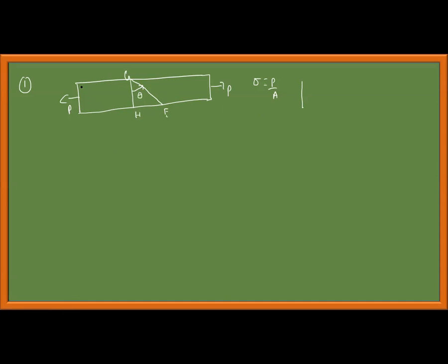Okay, the body is a long slender member, a bar. In the bar, if I take the stresses throughout along the length, the stresses are uniform. But if there is a plane at a certain angle in that bar, then the stresses are different. I need to find the stresses on that plane. As soon as you draw a bar like this, you assume it is 3D like this. Okay, and also there's thickness in this direction.